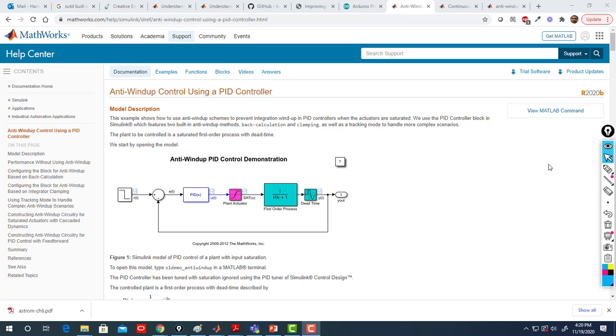If you inject the input at time t equals 0, maybe after 5 seconds your process starts to react to your input, a 5-second lag. This dead time sometimes causes instability of the system, and overshoot and a lot of problems.